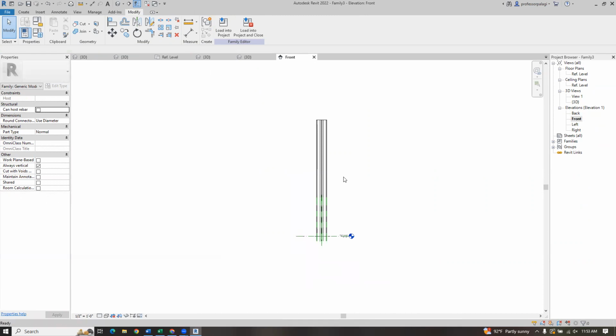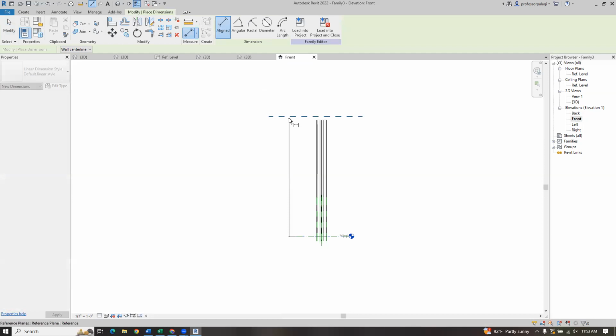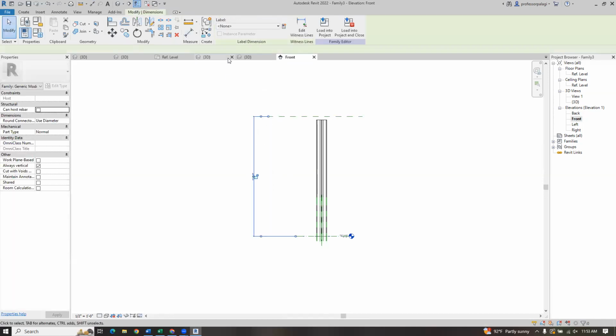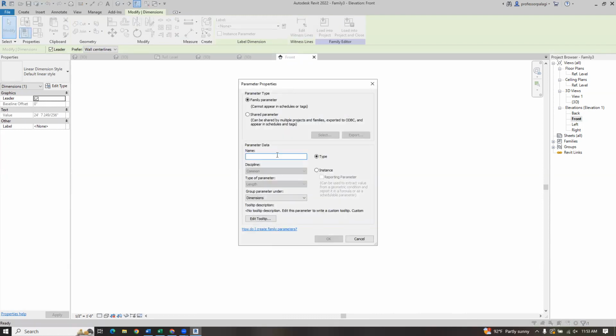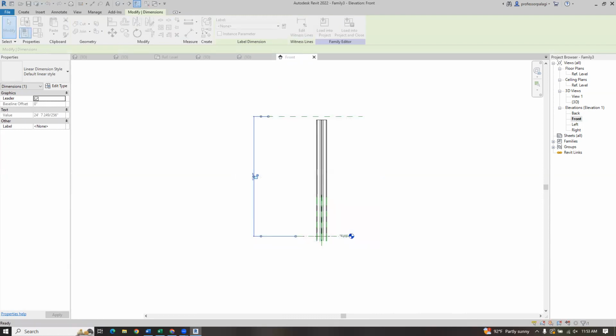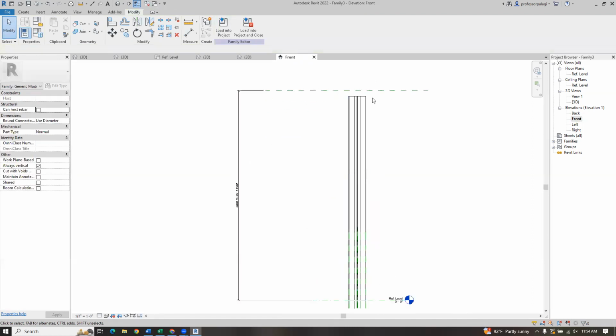Here. Do a reference line, draw another line here, and now I'm going to dimension this. I'm going to make this overall. Okay. Now this is interesting, in that we're going to want a column cap to this. This is going to be the plane where the structure is. This column doesn't go up to the plane. It's held back from it, right? How much is it held back? Let's say a foot, just to make it easy.